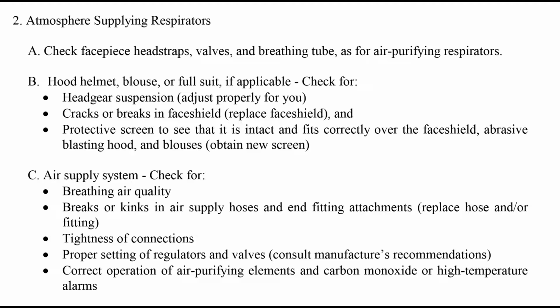Air supply system. Check for breathing air quality. Breaks or kinks in air supply hoses and fitting attachments: replace hose and/or fitting. Tightness of connections. Proper setting of regulators and valves. Consult manufacturer's recommendations. Correct operation of air purifying elements and carbon monoxide or high temperature alarms.